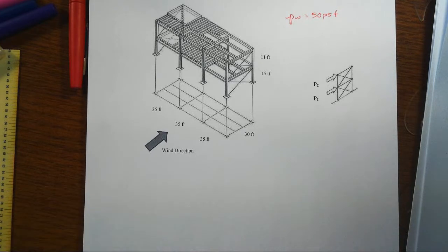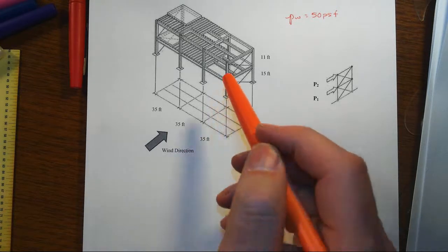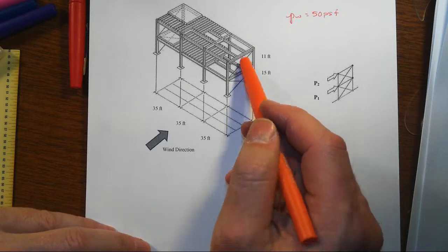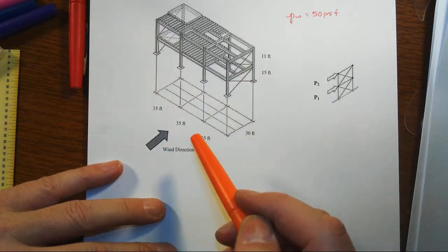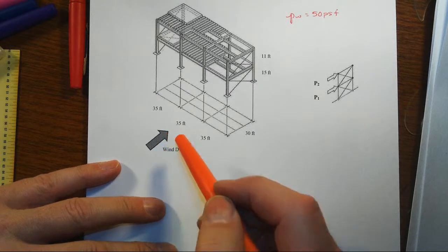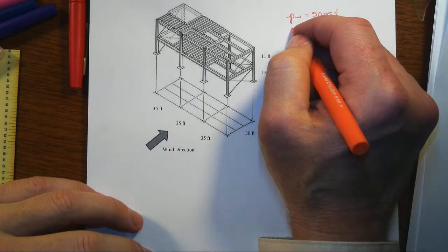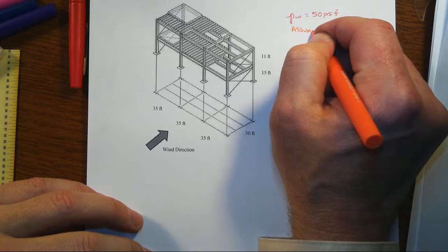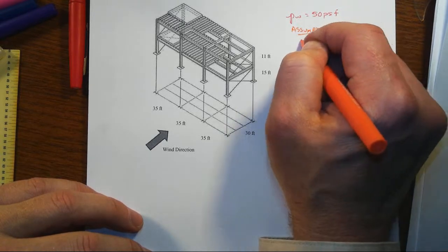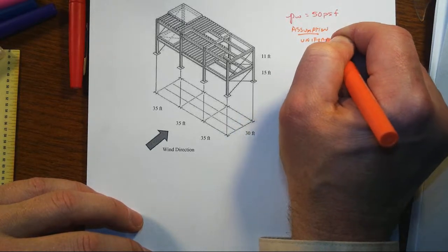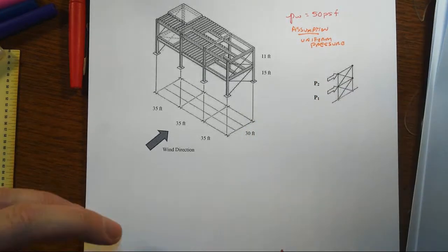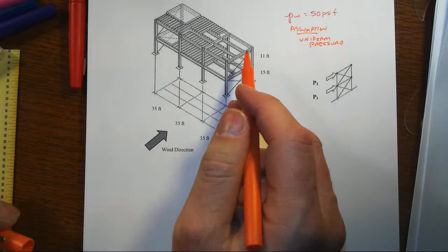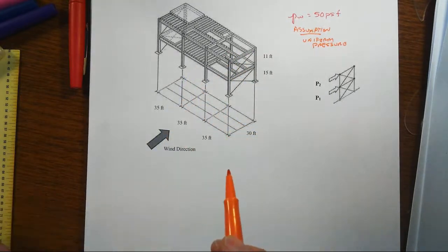So when we're thinking about that, we've got a relatively simple scenario here where the lateral force resisting system is at this end and the other end. We're assuming that the pressure is constant everywhere, so that's an assumption. And with that, whether it was a rigid diaphragm or flexible diaphragm, with this basically concentrically applied load, the load's just going to get split between the two.